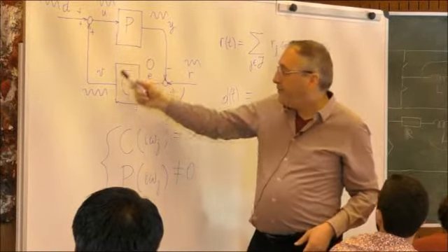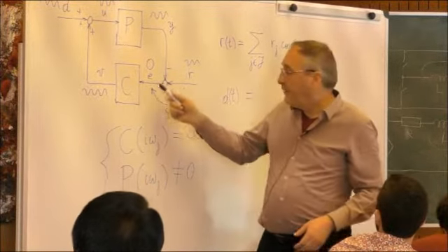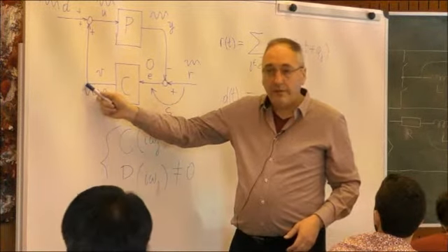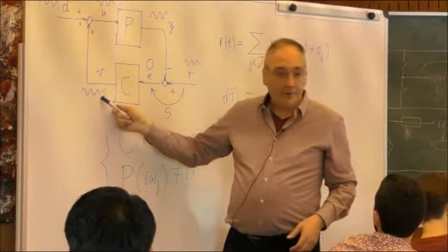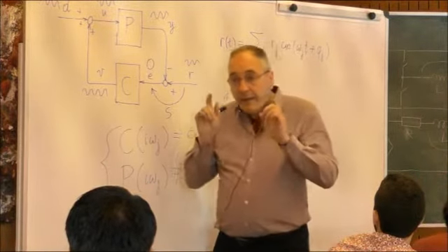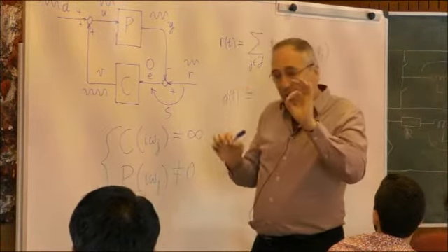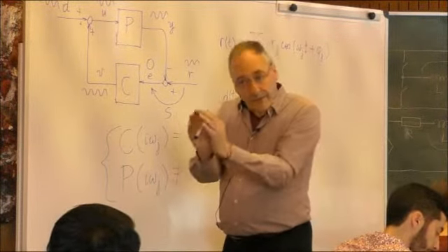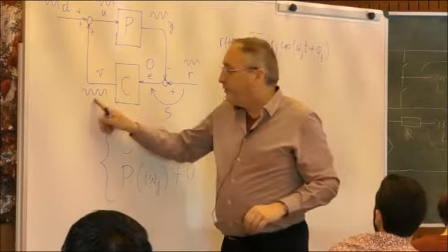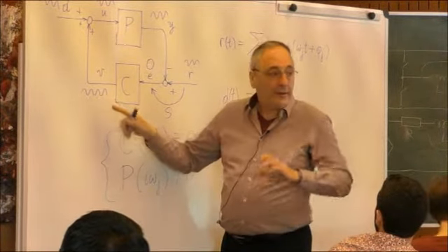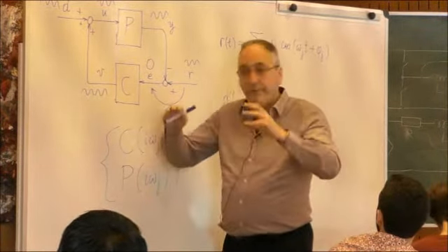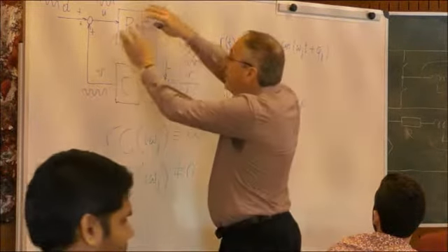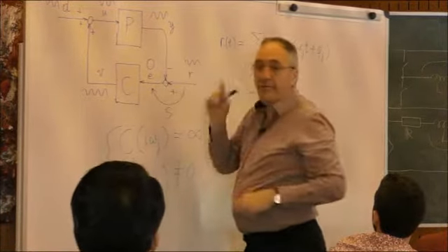So you see this controller receives no input, but it produces a superposition of sinusoidal signals, which is exactly what is needed, at exactly the correct amplitude and phase, because it cleverly reaches that situation, so that putting everything together, E will be 0.